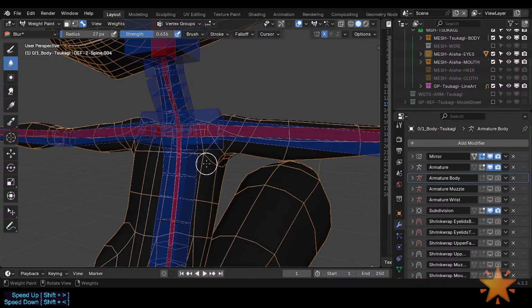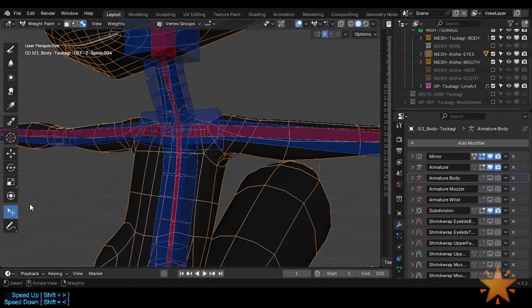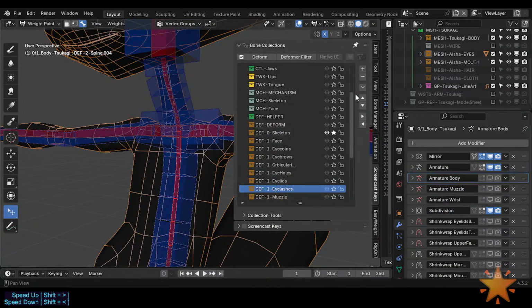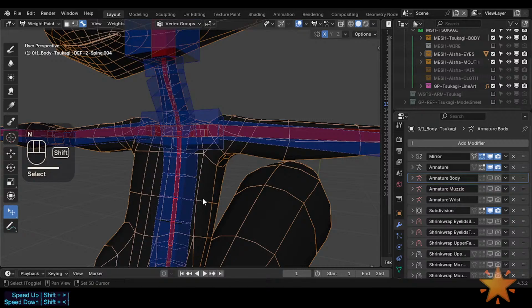And so I don't need to go on edit mode because in Blender, recently, some Blender 4 version, I don't know exactly when they brought this up, we tweak here. The shortcut doesn't work for some reason, but we click here, and here I can Shift Alt left mouse button, click on a face loop. Sorry, screencast keys.